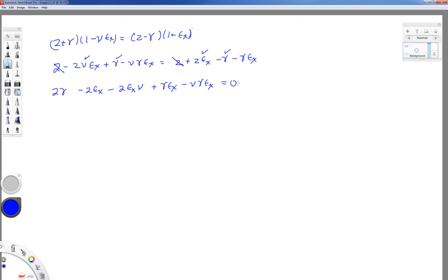All right, now here's something that we need to talk about a little bit too. For engineering materials that we deal with, we typically have very small strains. That's how we made the tangent gamma approximation. If we do have very small strains, we're talking about something much less than 1. Even 0.01 would work, but 1 times 10 to the minus 3 to 1 times 10 to the minus 6 is a typical engineering strain range.